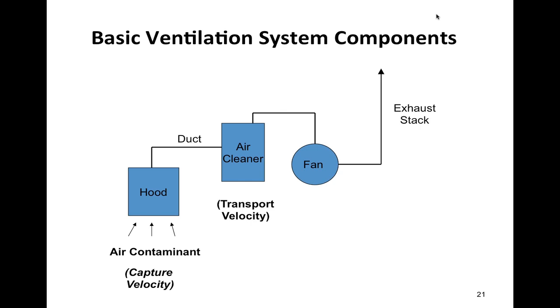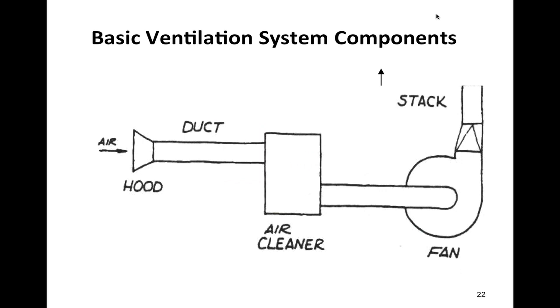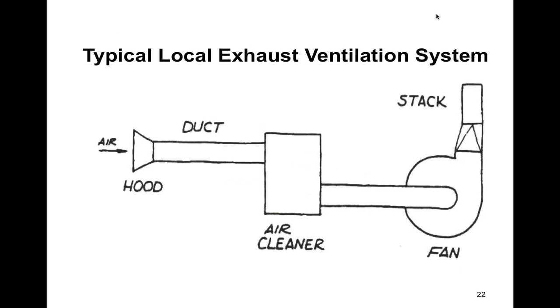So you may have seen these guys use a rig where they have a device with a filter and an exhaust fan in it, and ductwork, maybe 6 or 8 inch ductwork, goes up to kind of a movable arm, almost like a robotic arm that he can grab and pull. It's got a shrouded exhaust hood on it that he can pull right to the place where he's welding something, and turn that fan on, and it sucks that material away from him. And he can move that into the next room if he's welding pipe in the next room. And he can manipulate that so that if he's got to work on this side, it's pulling the particles away from him.